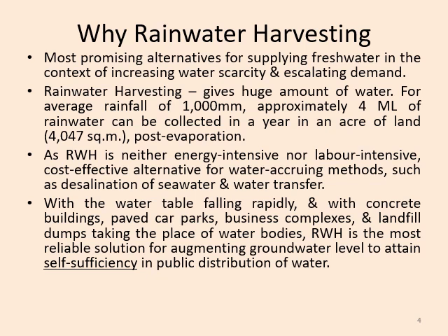The time here is considered for a year, and the area is considered an acre of land, means 4047 square meters. Over a 4047 square meter area, for 1 year we can collect 4 million liters of rainfall if the rainfall happens at an average depth of 1 meter.